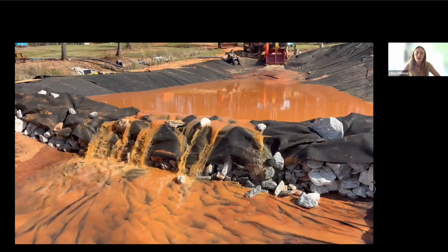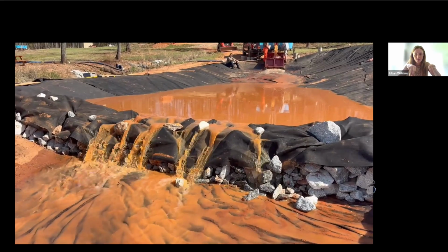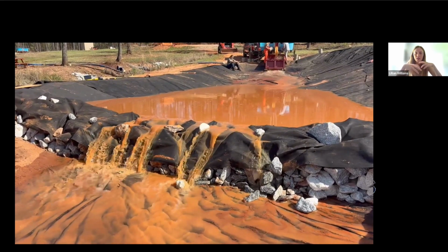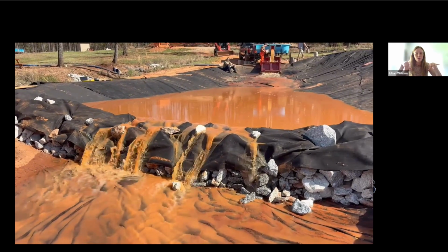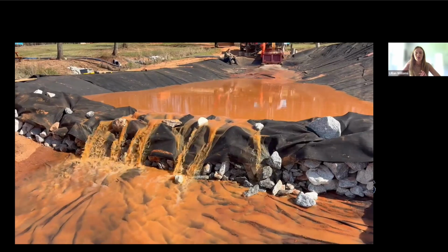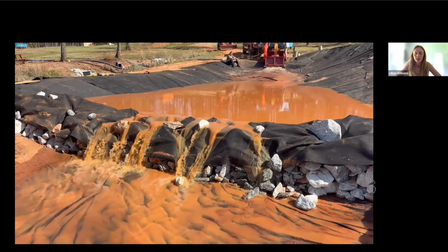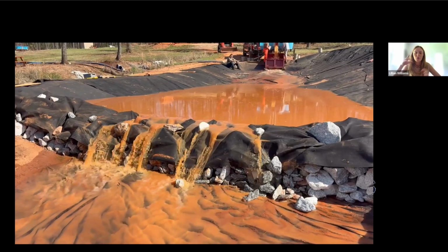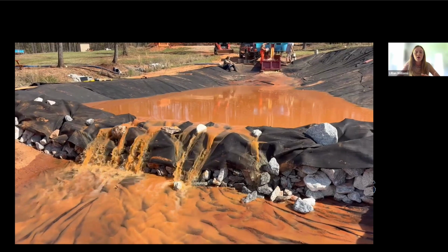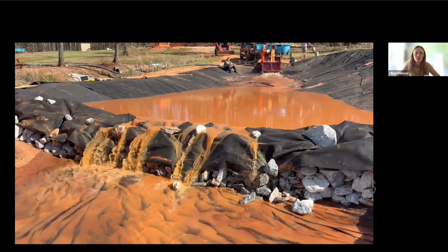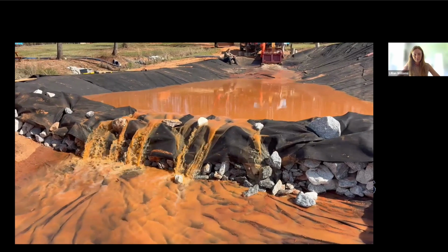Here you can see the rock was placed on top to hold that fabric down, so you weren't needing that stapling or any other type of secured method. And there was no trenching of the rock, because many studies had shown that was not helpful and really just adds expense. And then the geotextile generated higher impoundment, but the weep holes were able to reduce excessive dewatering periods. So this resulted overall in increased sediment capture and decreased discharge turbidity than just a traditional rock check.